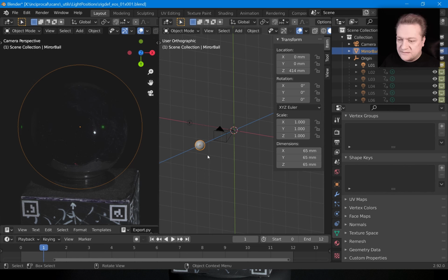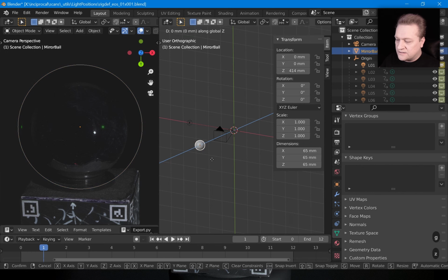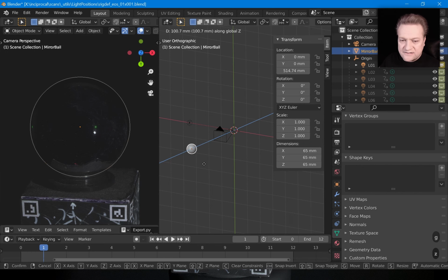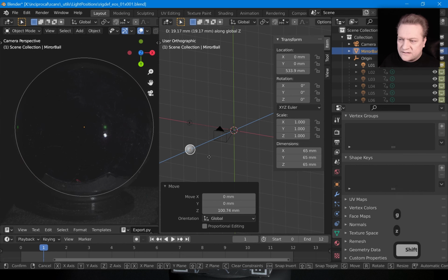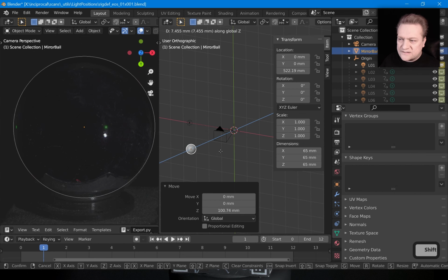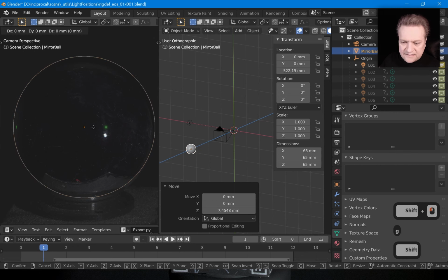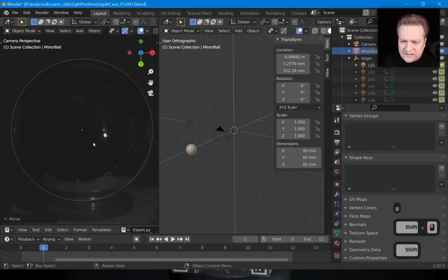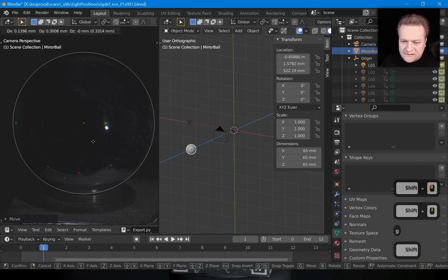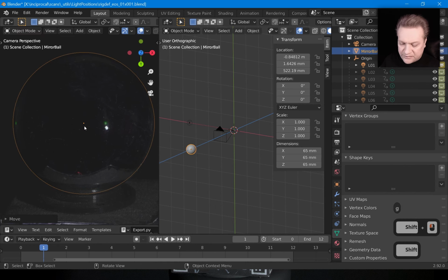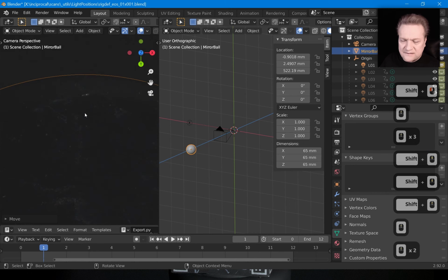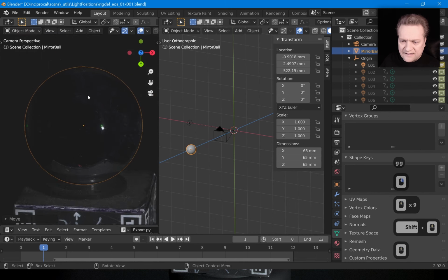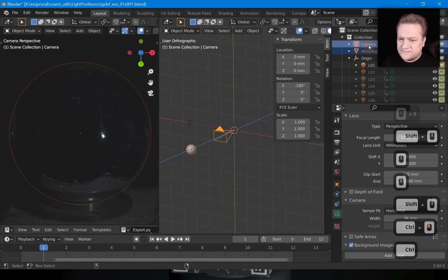In this case, in Blender, I hope you can see all these shortcuts. I click G and Z, and by moving it back and forth, we can make sure that it's the same size. I think that should be pretty close. And now, while I'm in this window on the left, I can press G in Blender and just move it around until it aligns, and we try to do it the best we can. I think that should be pretty good.